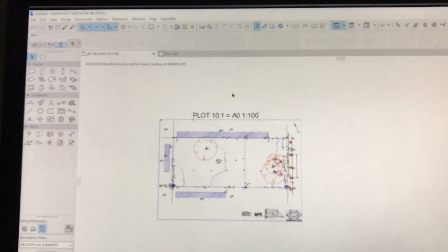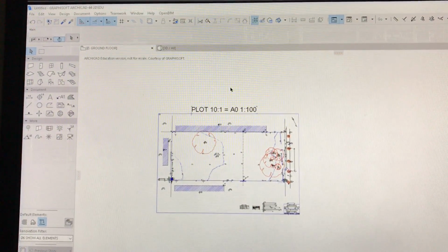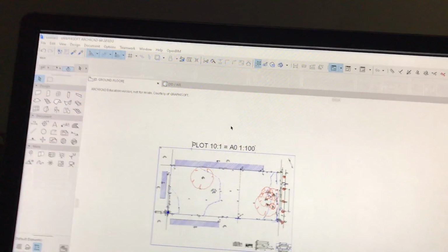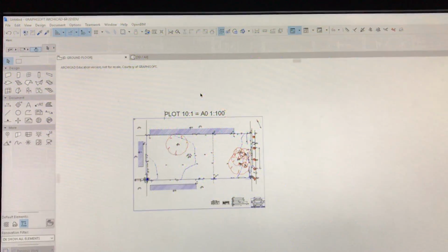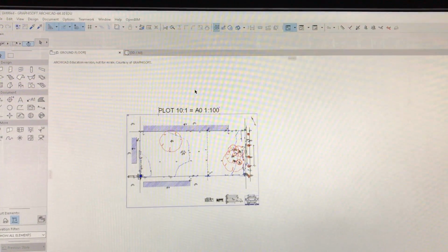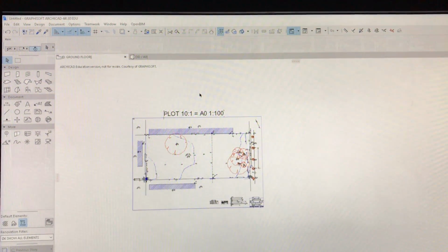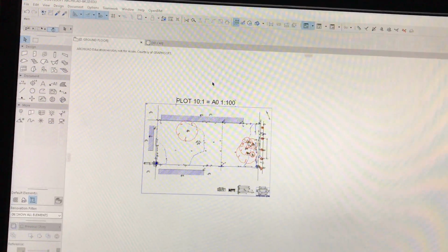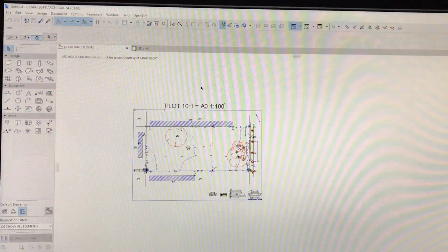That's important because when we are creating our layouts later, bringing everything into the layout book, we've got all of those combinations for the drawings. We cheated a little bit in the courtyard house by saying show and unlock all, but you're going to get to the real job of saying I've got structural plans, electrical plans, overhead lighting plans, etc. Those layer combinations become important.